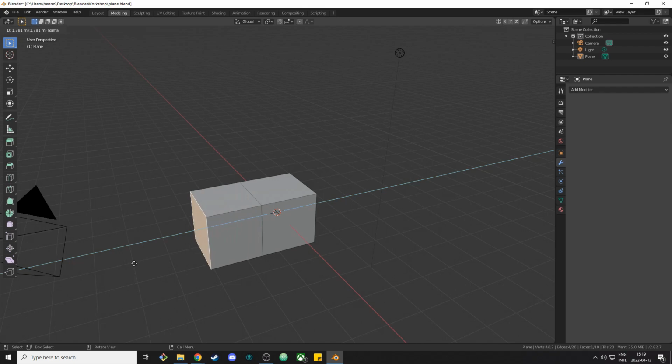That means I will add the geometry necessary to connect this face with the cube there where it was before, and I automatically go into grab mode or move mode to move the new geometry where I want it to be.